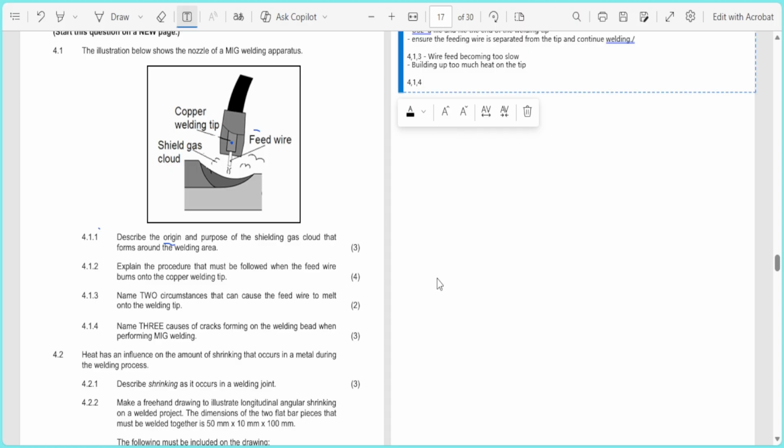So this means that parts can't move freely. When welded, they cannot expand and contract naturally, so they can crack under stress. Think of welding a thick tractor frame. If you don't preheat it, the sudden temperature change is like pouring boiling water into a cold glass. It's going to break, obviously, right? So proper technique, correct settings, sometimes even preheating are your best defenses against something like this.